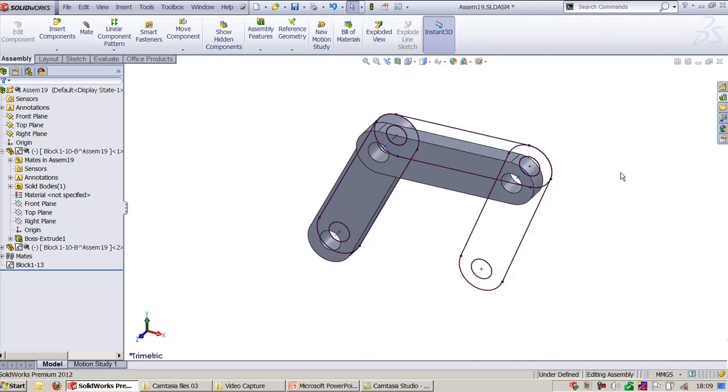So what exactly is this virtual component? When you are creating the design in the top-down approach, that is, you have only the rough sketch and you are going to create parts and you are undergoing a number of iterations, then definitely this approach will help you to create the model, because the part will be saved internally, not externally. If required, you can make it an external file.